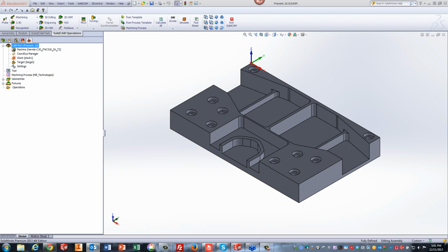Now, we're actually doing a demonstration on two different parts, this one and another one right after it. And what I'm going to do is first I'm going to put a 3D iMachining 3D path on it, and then I'll go back and start doing it in iMachining 2D, and we'll see the difference as far as time goes, as far as programming the part itself, and why we actually prefer, in certain cases, to do iMachining 3D on prismatic parts rather than the traditional iMachining 2D. In both cases, you should know, however, you'll always get the iMachining efficient toolpath that you need. But, well, let me stop explaining these things and actually start showing you what I'm talking about.